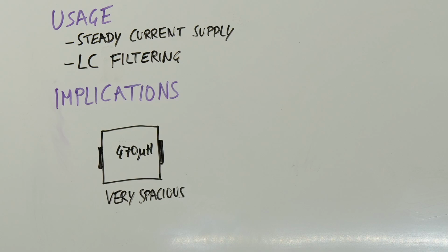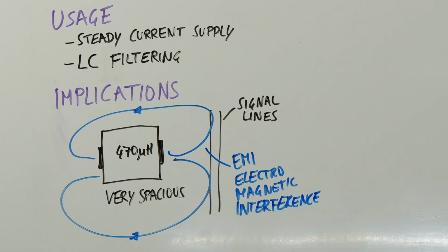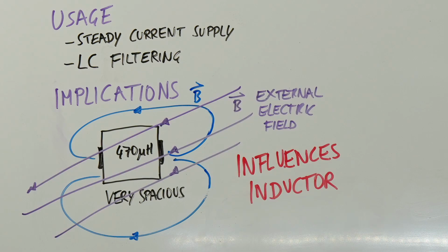When creating the layout, we must carefully consider their placement so that their magnetic field does not influence signal lines or integrated circuits, and so it isn't influenced by a magnetic field itself.